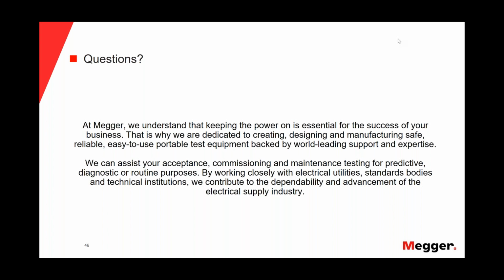Well, that depends a little bit on how you do the PD testing. Normally, when we do single-ended measurements, it doesn't have that big of an effect compared to when you make measurements in the return circuit. Then the condition of the neutral is very, very important, and corrosion would be detrimental. But also when we do single-ended measurements, if you have a really badly corroded neutral, it will create issues on your PD measurement.